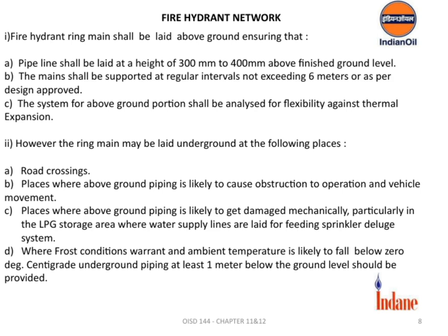Support is critical, so the mains need to be supported at regular intervals, not exceeding 6 meters, or as per the approved design. Proper support ensures stability and prevents undue stress on the piping. Additionally, the system for the above-ground portion must be analyzed for flexibility, especially against thermal expansion, to avoid stress and potential damage during temperature fluctuations.